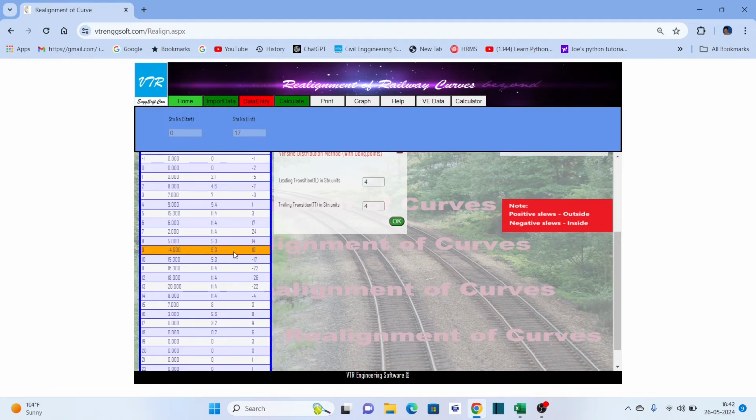This is the problem as far as this case is concerned. But it being a flatter curve, there is a variation that seems to be slightly more. But if you have a very long curve, like a 1 degree curve, 29 mm, or 2 degree curves and all, the versines will be 29 mm, 58 mm. In that case, this variation will not be much. Okay. Anyway, we'll see the next curve, check how much slew we are getting, and we'll see here.